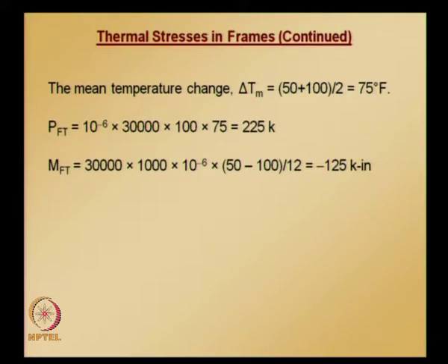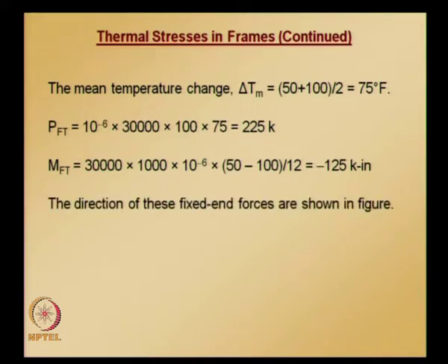and also here the calculation for fixed end moment is also given, and if you carefully observe, even in the fixed end moment equation there is no length quantity when you are calculating. So fixed end axial forces and fixed end moment are independent of length of element. So, these values remain same for both element 1 and element 2. So, using these values we can get the equivalent load vector. Direction of these fixed end forces are already shown in the figure.